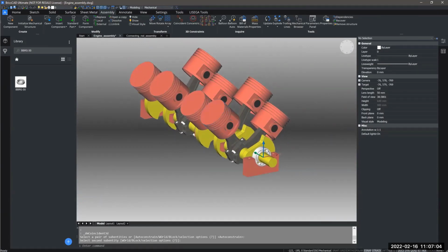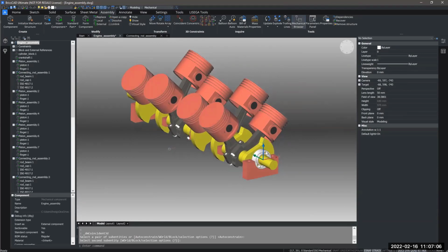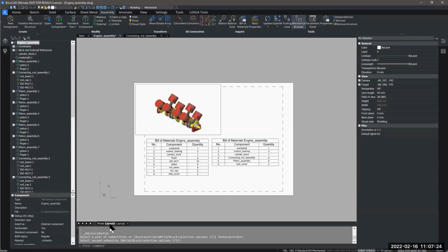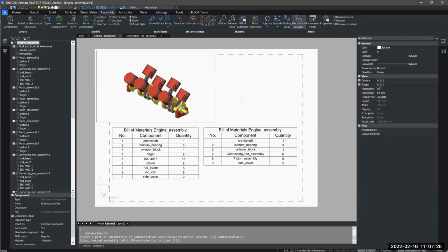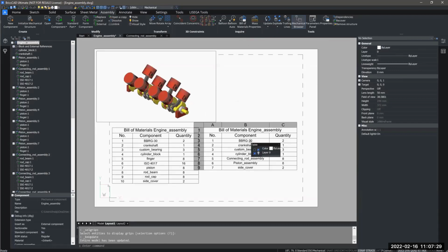So then we have added these components. These components are now inserted into the main assembly, meaning that they are not subcomponents of any other subassembly. So now, in theory, these ball bearings should appear in the bottom level bill of materials as well as the top level bill of materials. So let's go and check, and maybe I am proven wrong, but probably yes. You can see here the ball bearings now appear in the top level bill of materials with a quantity of 2, and they also appear in the bottom level with a quantity of 2 as well.